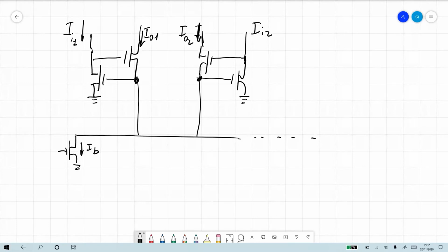So it's essentially what we have seen already, except that we get current that is going directly into the current conveyor input. And now we have to see what's happening. We just analyze the circuit, what's going on with the outputs as a function of the input. So again, remember current mode, we assume the signals are currents, and we look at what is the output versus the input.